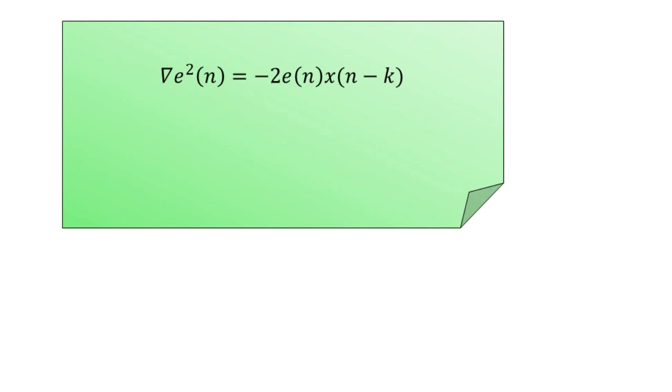Therefore, additionally we have hard limits placed on the step size. Here we denote the variable step size mu(n) of k as greater than mu minimum, whereas it is less than mu maximum. This is in order to ensure that the VS algorithm, the variable step algorithm, will converge in the mean with only a modest increase in computation, and the VS algorithm may result in a considerable improvement in the convergence rate.